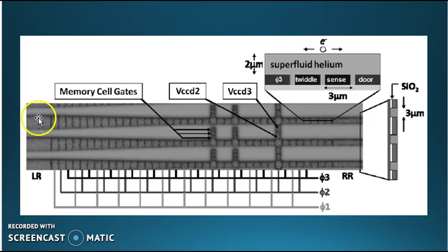This image represents 3 of the 120 parallel channels in the Bradbury device for rapid and accurate electron transport. This side cross-section shows the silicon dioxide layer, used for shielding the gates from one another. In this image, the dark gray represents the electron layer floating on the liquid helium. The light gray represents the metal interconnections in the device. The line patterns in this image represent gates.